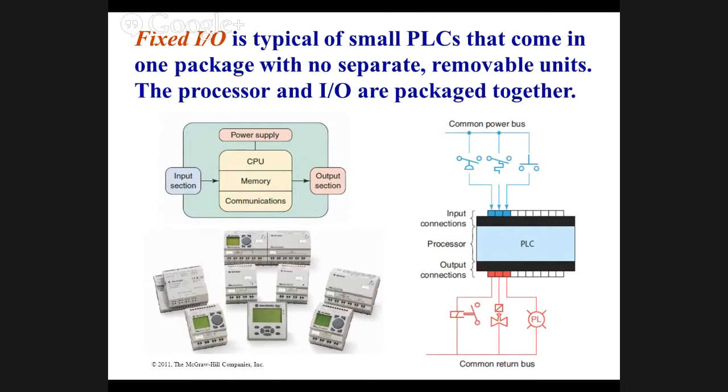Now, what we showed you on that packaged CLX controller is a fixed I/O system. When it says fixed I/O, that's sometimes referred to as a shoebox PLC. It basically means that the I/O and communication is built onto the PLC. If you burn out something, you have to move the wire, change the program, or throw it away and get a new one. There's no fixing it. It's fixed I/O.